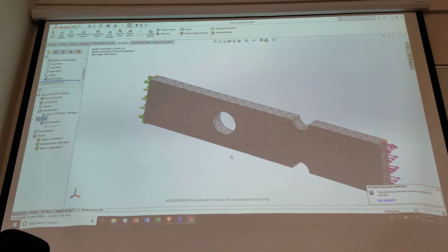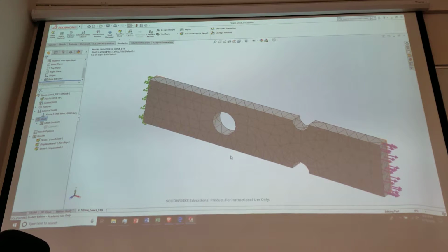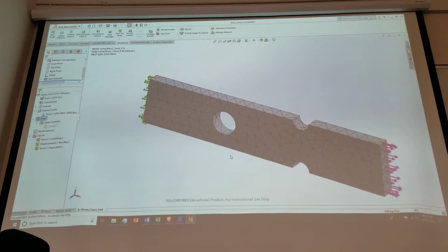Okay. Adding in nodes. And some of the ways we tell when we have problems is that we look for areas of high stress gradient. We don't like adjacent nodes that are at significantly different stress levels, because any error in those calculations can be way off. So we tend to search for things that are smooth, or where the gradient between them isn't particularly high.